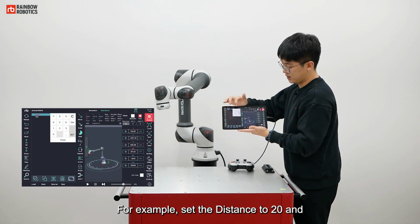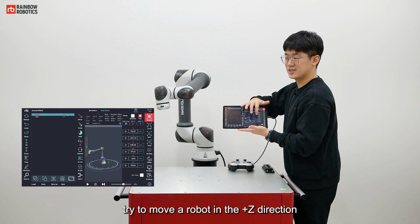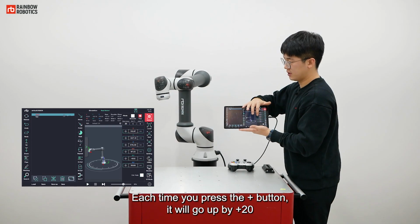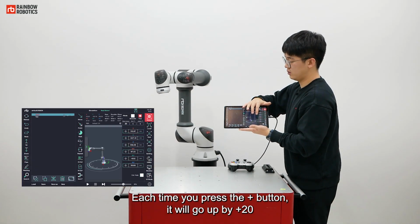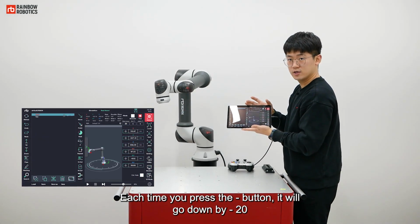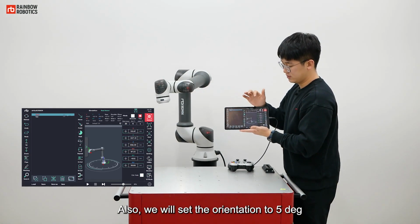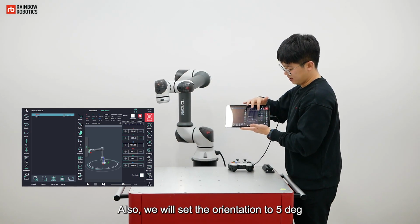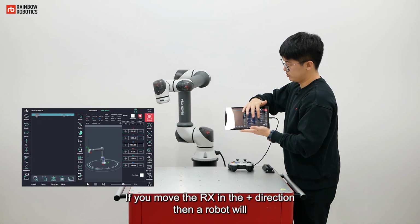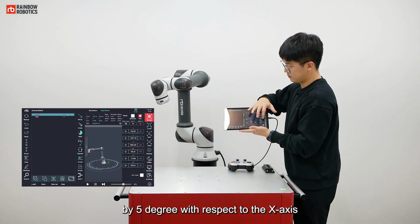For example, set the distance to 20 and try to move a robot in the plus Z direction. Each time you press the plus button, it will go up by plus 20. Each time you press the minus button, it will go down by minus 20. Also, we will set the orientation to 5 degrees and enter a rotation value in the x direction. If you move the Rx in the plus direction, then the robot will rotate by 5 degrees with respect to the x-axis.